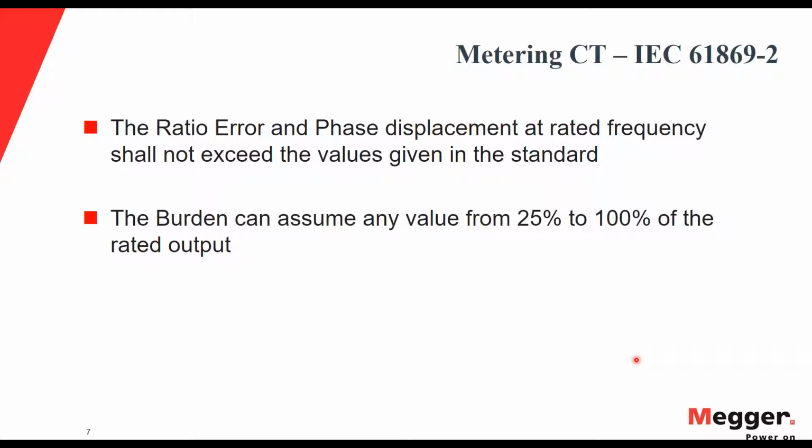For example, if you have a 1000 to 1 CT, from 200 to 1000 ampere is your rated range, or the most accuracy you will get. Although there are some special cases or special classes that can give you a higher accuracy at lower percentage of rated current.